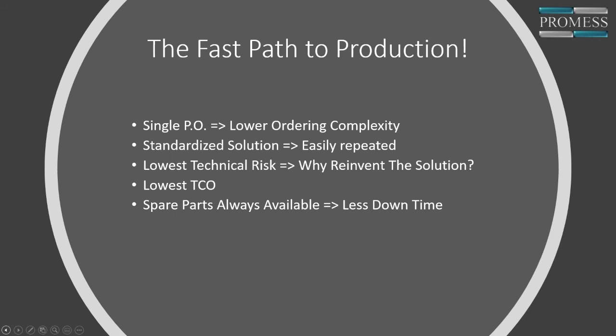A lot of times the spline shafts introduce some error, but one thing we can do in our system that helps reduce the amount of error is calculate the amount of lash in the tooling and then compensate for that. So there are air collets used all different ways. I've seen jaws used as well, a 3-point jaw type end effector on the end of our units. But I imagine you have to be careful too, John, about damaging the shaft. I think that's a critical thing. Yeah, there's always a balance between that, for sure.